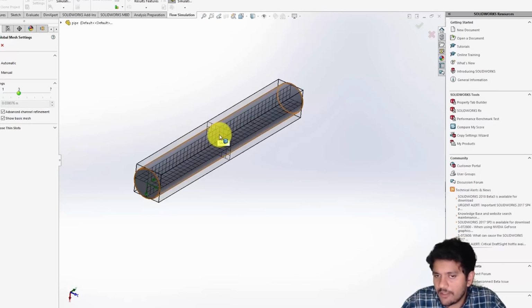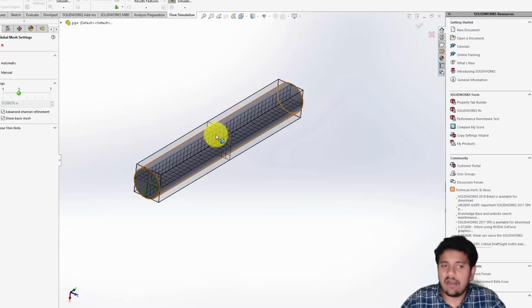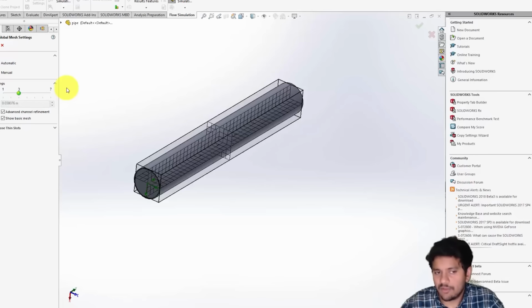Now here you can see that along X, Y, and Z, your mesh looks square, right? Which means in 3 dimensions, it's going to look like a cube. Now that is what is called a hexahedral mesh. Hexahedral meshes can be generated very easily by using something called a binary tree or an octree data structure approach. Okay, and we'll be talking about these algorithms a bit later. I'm not going to be talking about them in too much detail because this is still an introductory class.